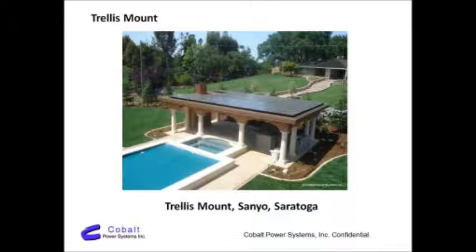So it's pretty easy to wash the array off with a hose with a good nozzle, one of those brass nozzles, and you can typically even sometimes stand on the ground and direct a stream of water up to the roof and hit the whole array. And you just want to wash it down once, wait 5 minutes, wash it down again. So you don't really need access. And then if there were to be some reason why we would need to get access to a solar panel in the middle of the array, that's our problem, not your problem. And we would take modules off to get to the middle, but we almost never need to do that. Okay, so that's a trellis mount.